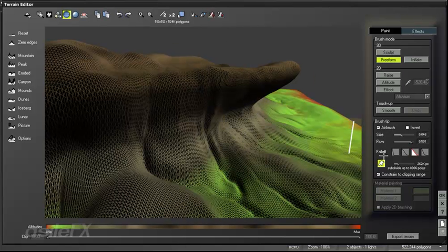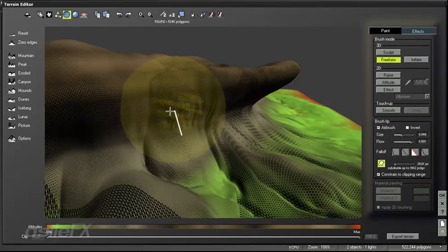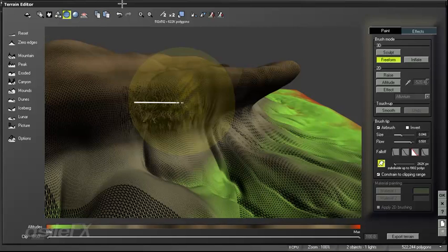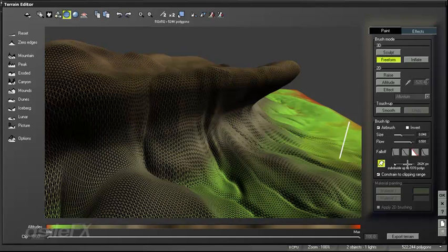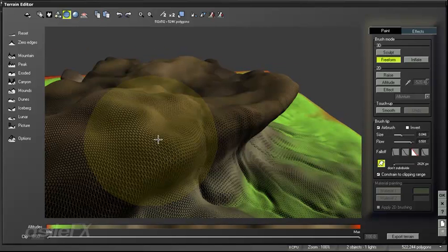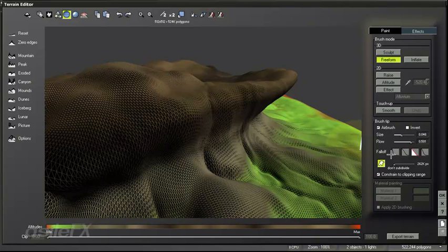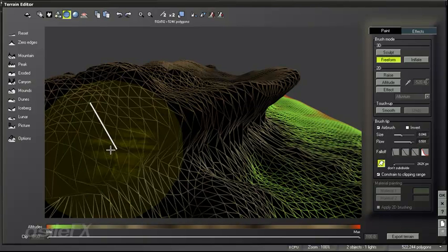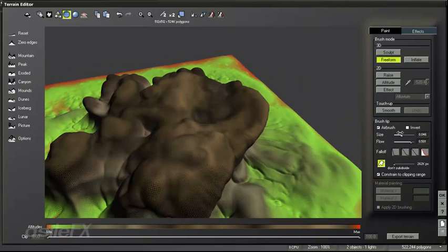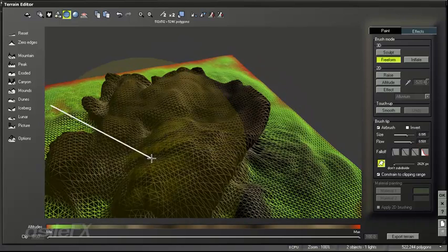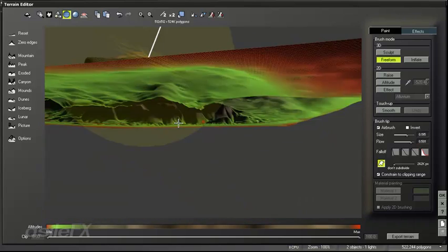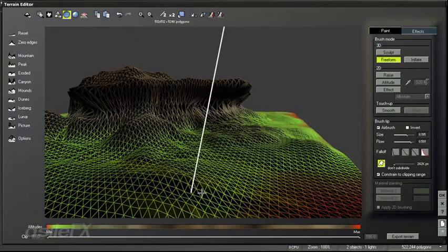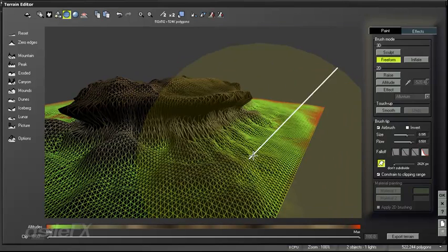You want to be careful when using the subdivision that you either keep at a very low amount if you're going to be going equally throughout the terrain. Typically, I just like to keep it off. I'd rather have it as a modifier to work with a filter to modify the geometry rather than dividing the mesh because of some of the current problems.